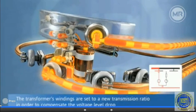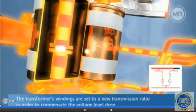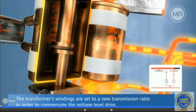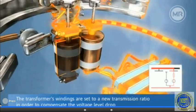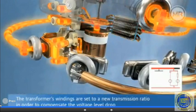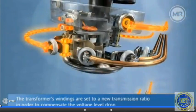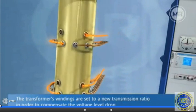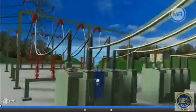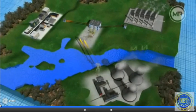Now, the two contactors that we are talking about are clearly visible here, along with certain vacuum-based contactors, which are chosen to further decrease the sparking that can happen in the operation of an online tap changer. Now, the tap change connects a larger part of the winding to the circuit, and hence the voltage dip is compensated by the system.